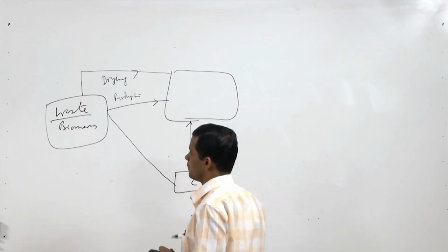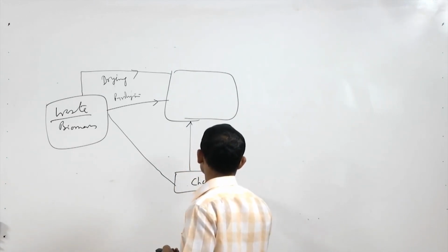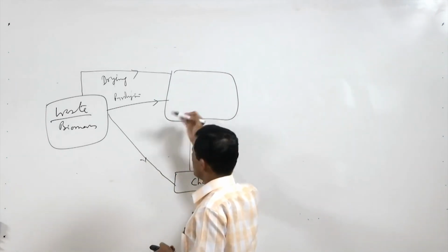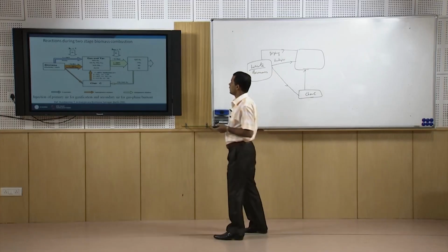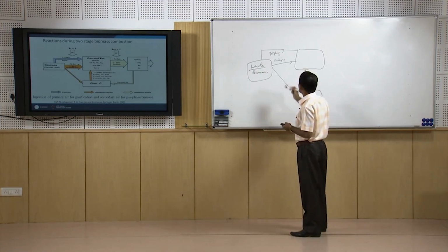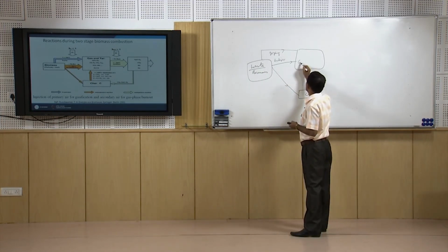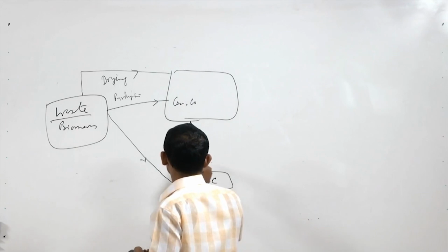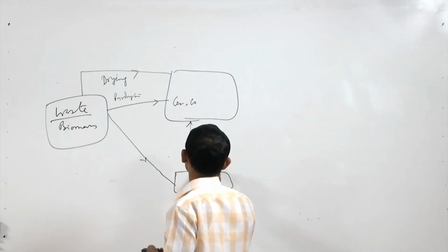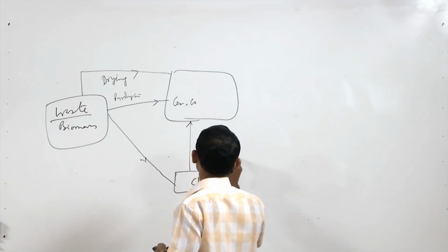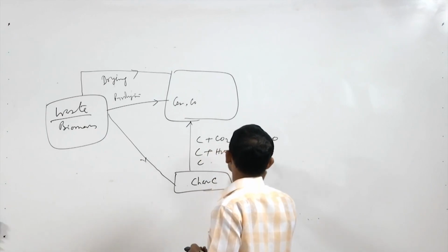So, this is char, carbon, and this is pyrolysis. So, pyrolysis will obviously give the volatiles, the light hydrocarbons, it will give us CO etc. So, these are the reduction part. So, once this pyrolysis is giving us CO etc., here the carbon will be reacting with CO2, reacting with H2O, and it will give us 2CO, it will give us H2 plus CO.